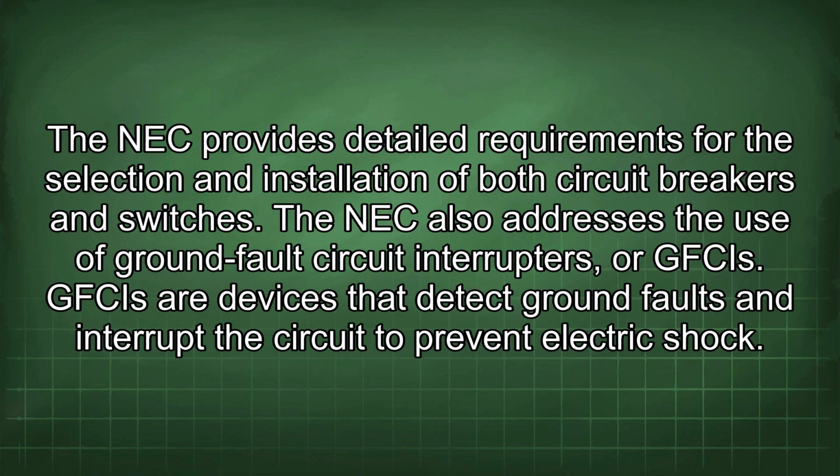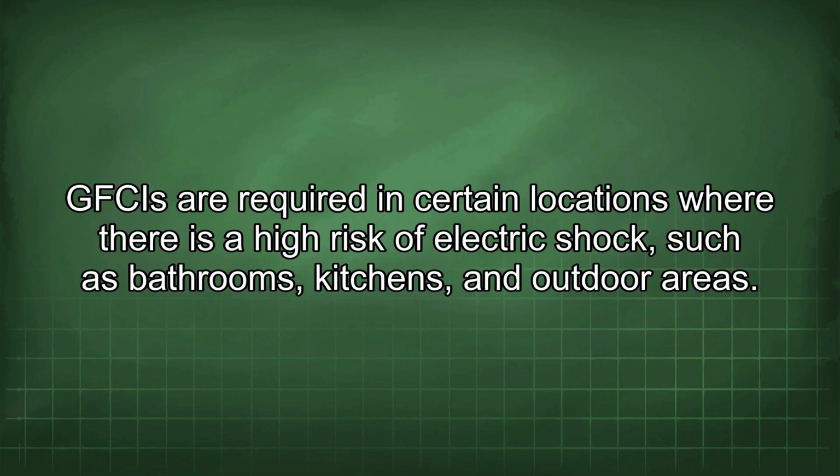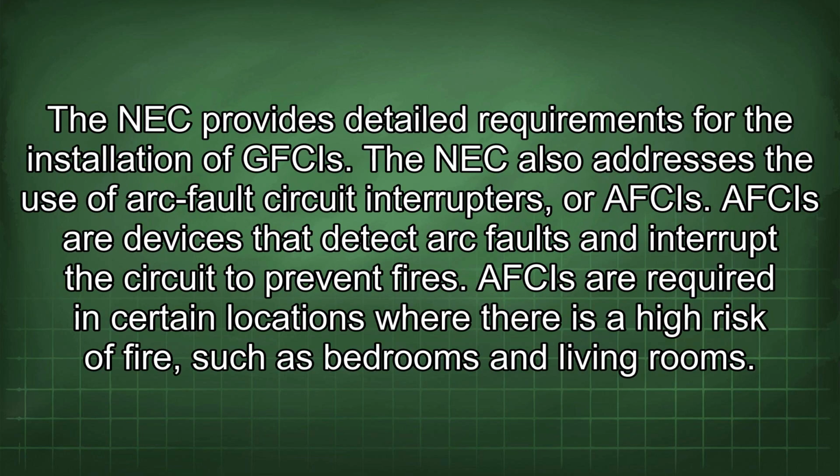The NEC provides detailed requirements for the selection and installation of both circuit breakers and switches. The NEC also addresses the use of ground fault circuit interrupters, or GFCIs. GFCIs are devices that detect ground faults and interrupt the circuit to prevent electric shock. GFCIs are required in certain locations where there is a high risk of electric shock, such as bathrooms, kitchens, and outdoor areas. The NEC provides detailed requirements for the installation of GFCIs.